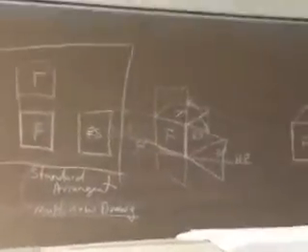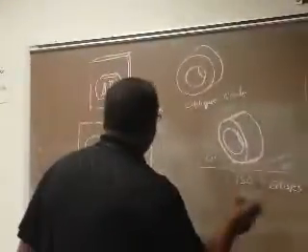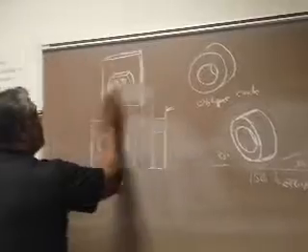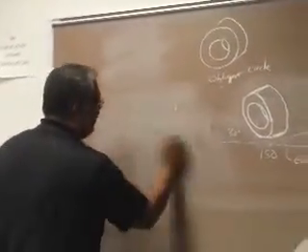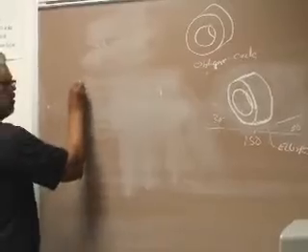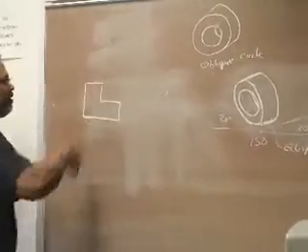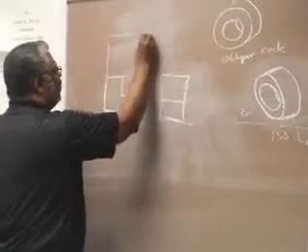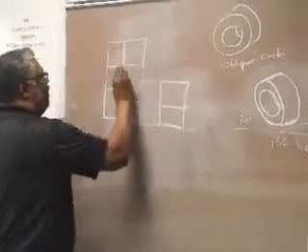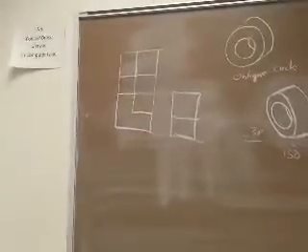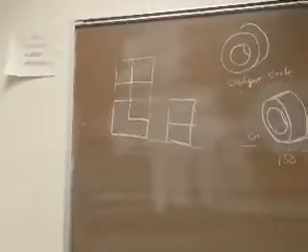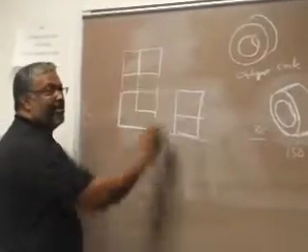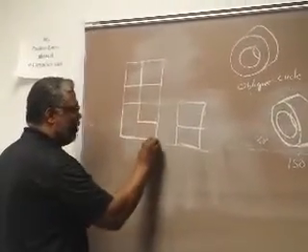Now that says usually the front. Well, it depends. It's usually the front, but it could be other views as well. So let's say, for instance, we have an object, and it's the stair step. We'll just say that's our front, and then this is our right side of the object, and then this is our top. Well, when we look at those three views, which view is more descriptive? The front. Yeah. Because this doesn't tell me much, this doesn't tell me much, but at least this gives me a shape of the object.